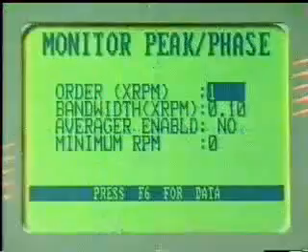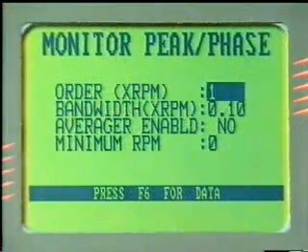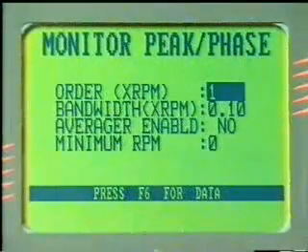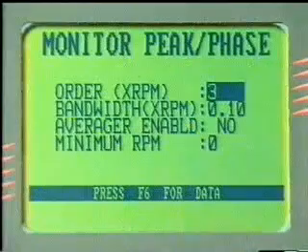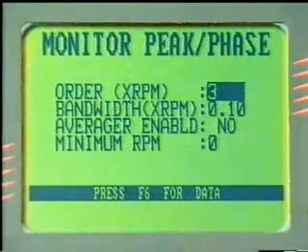All of these measurements have been using the 1 times shaft speed and filtering out all other frequencies. However, a multiple of the tach pulse frequency can be monitored by entering that number here, which then invokes a filter around that band. This feature is valuable for some applications.